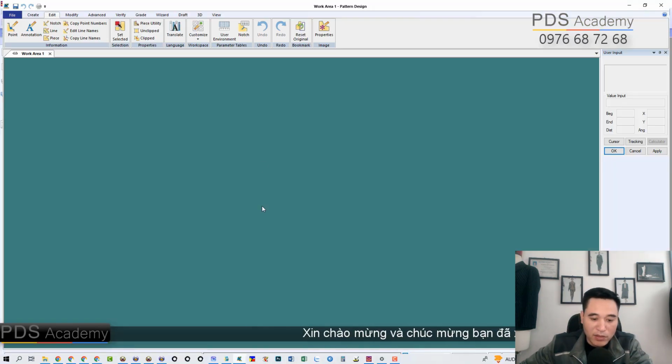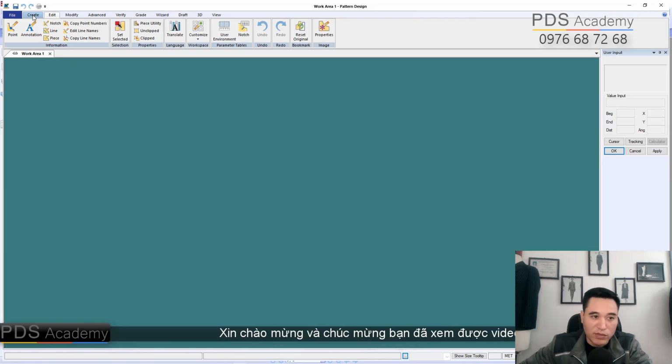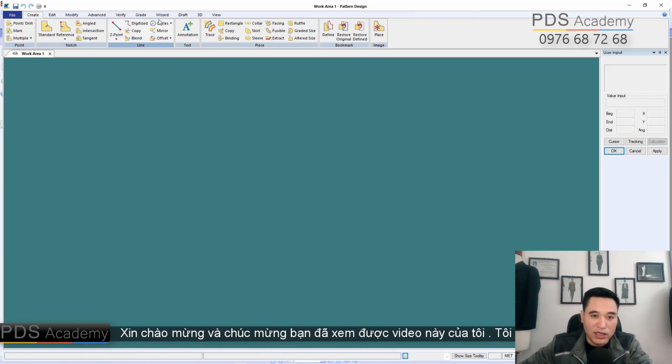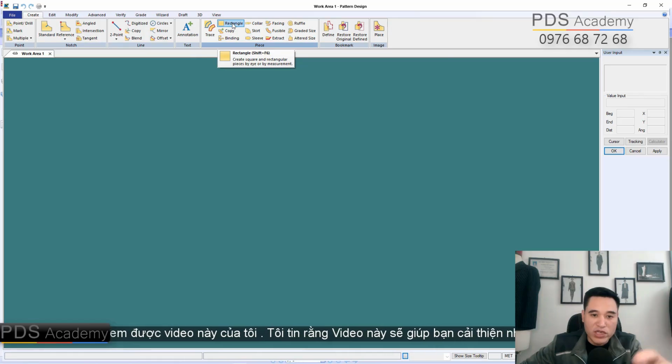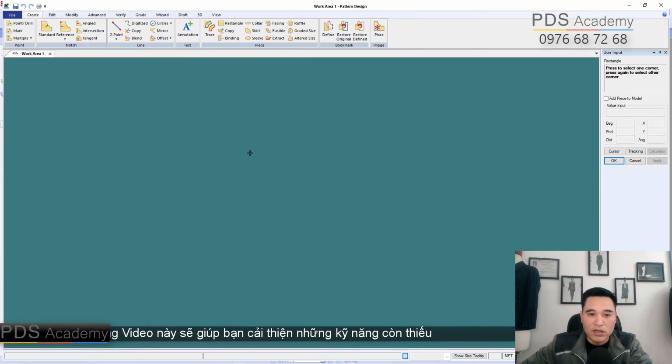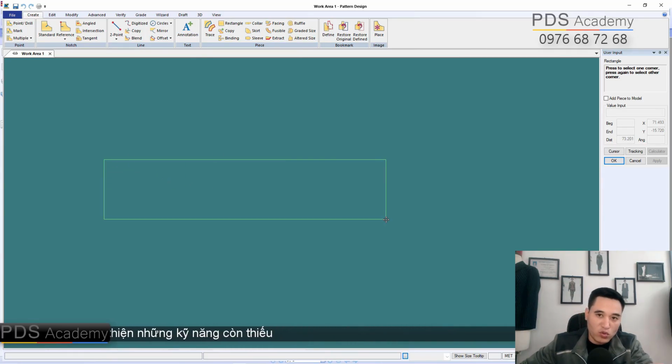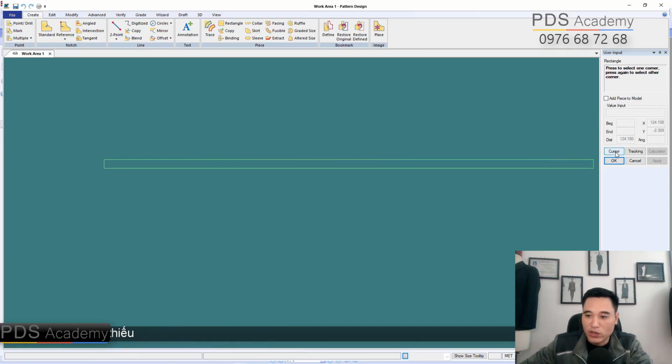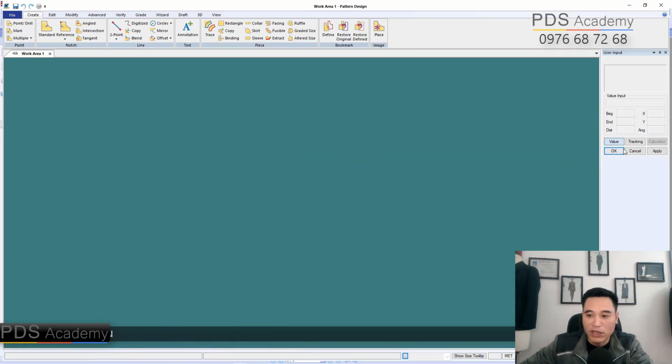Now you will open this design section and go into the create command. In this create command, you'll see there's a rectangle command, or you can press the Shift plus F6 key. The shortcut key is F6. Shift plus F6 works too, right? Then you left click in the middle area of the screen here. Drag it out. If there are any numbers, pay attention to this. On some computers, when you left click and try to drag, it doesn't move, right? So pay attention to this area on the right. This spot right here, it's the value field. If you leave this value here, and then you select the rectangle command, you left click. When you try to drag, it won't move.